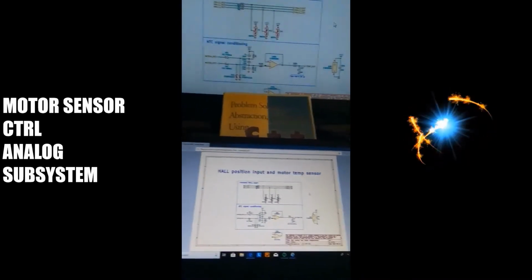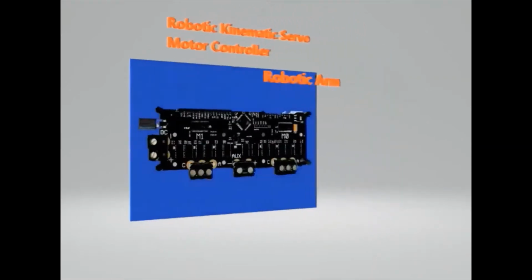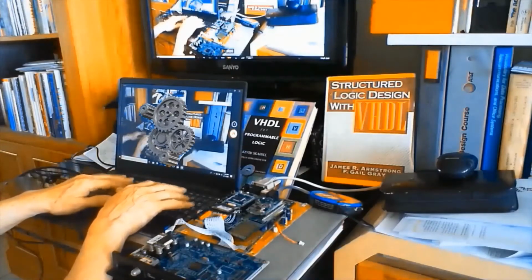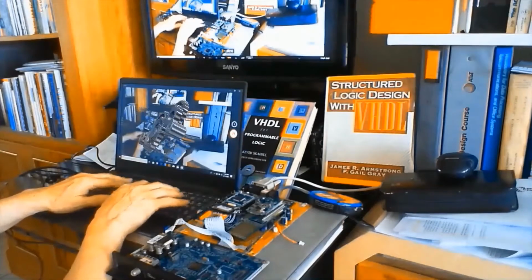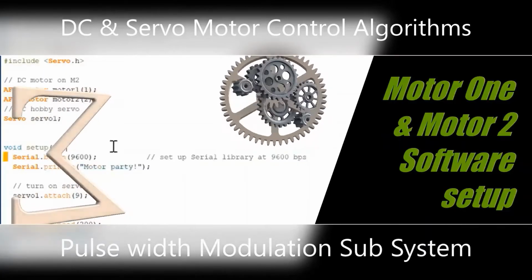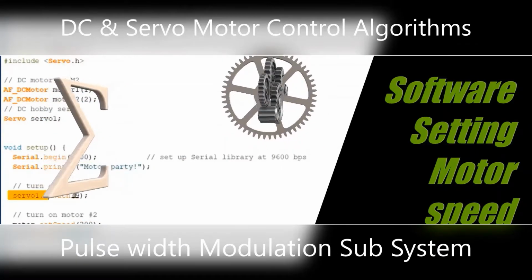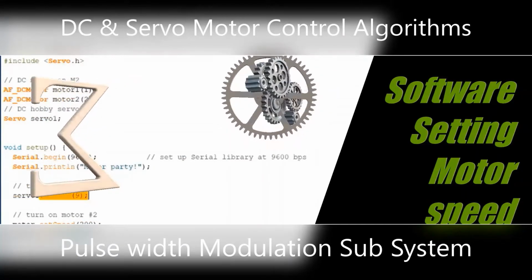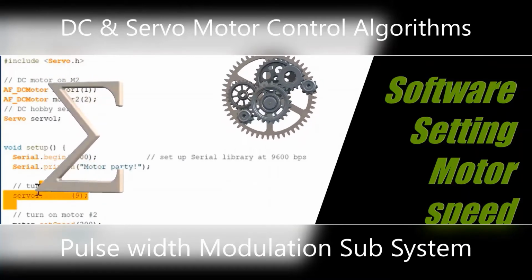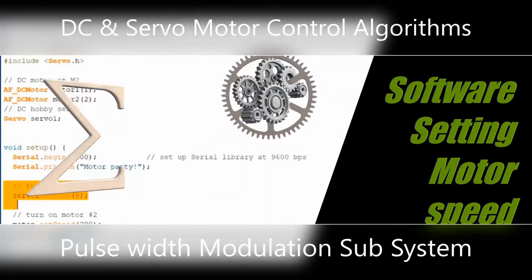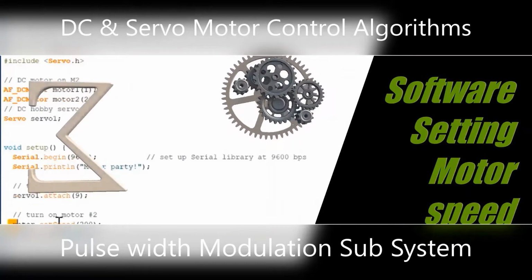The direction and style parameters are the same as for step, but one step steps exactly once. The release function removes all power from the motor. Call this function to reduce power requirements if holding torque is not required to maintain position.